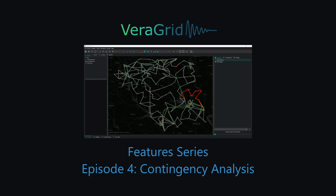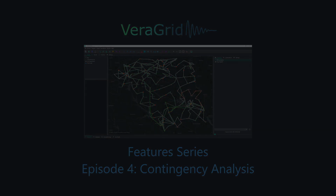In our last episodes, we explored how to model a network and solve the power flow and OPF under normal operating conditions. Today, we take the next step in the workflow. Now that we understand the base case, we turn our attention to what happens when something unexpected happens in the grid. That's the purpose of contingency analysis. Instead of simulating only the intact network, we test credible outages like losing a line, a transformer, or a generator, and check whether the system remains secure.